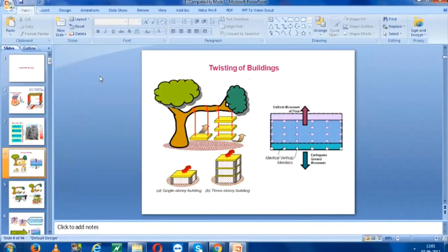Single story building, 3-story building, we have a translation motion. We have kept the things quite same from top to bottom. Although, as you can see, the one having long strings will have large displacement and large time period and low frequency, as compared to the multi-story one, which has 1 degree of freedom and 3 floor levels.